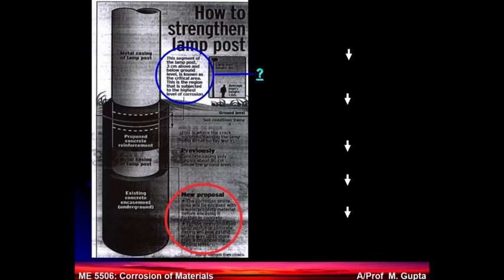Crevice corrosion, that's correct. When the people play, the mud can splat and make a deposit on the lower portion of the pipe, which based on their observation is about 3 centimeters above the ground. Crevice corrosion. Under-deposit corrosion, that's the likelihood.